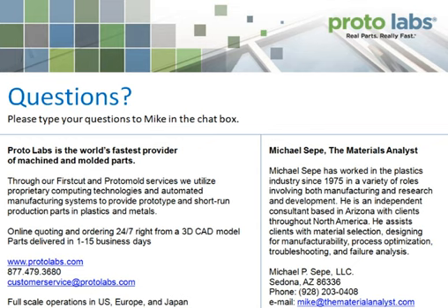So normally, when you do color concentrates and you have a UL approved part, you have to go through an approval process with UL so that UL is satisfied that the colorant that you're using and the way you're using the color is not compromising the rating that they've published for the base resin. And it's a lot of work, but in many cases it can still be worthwhile.